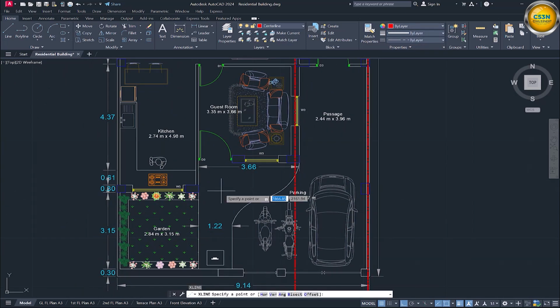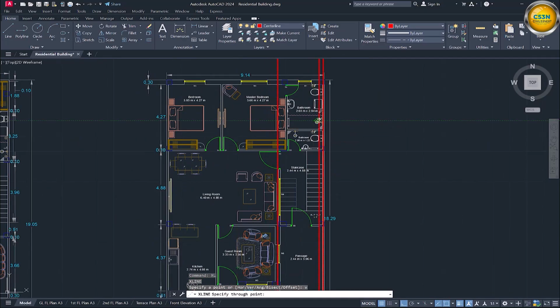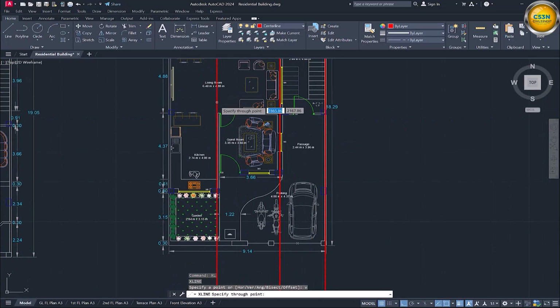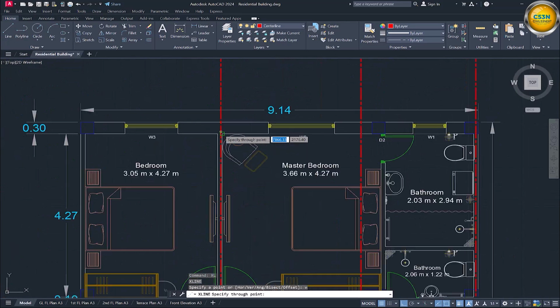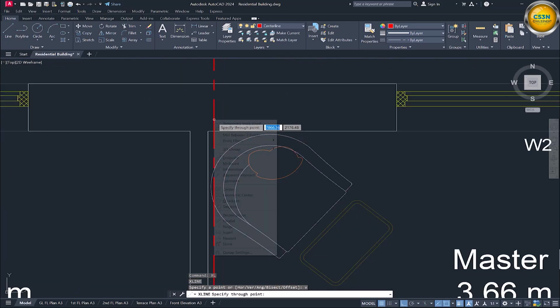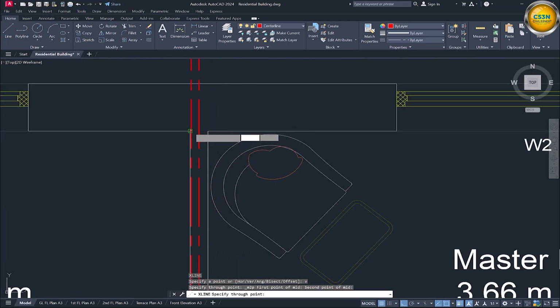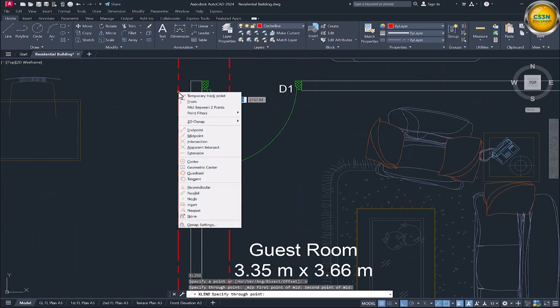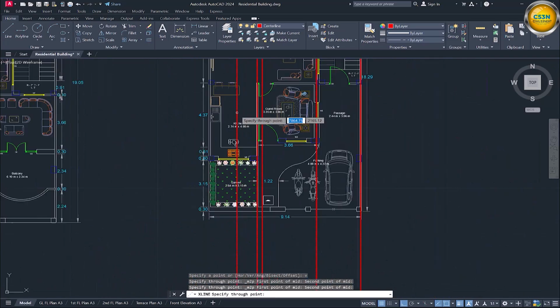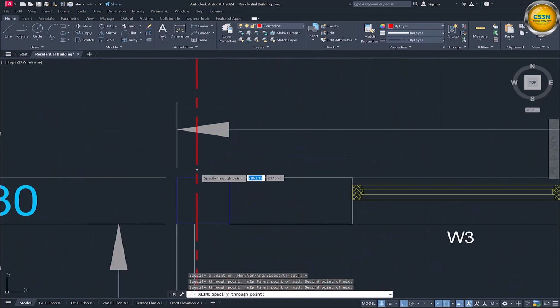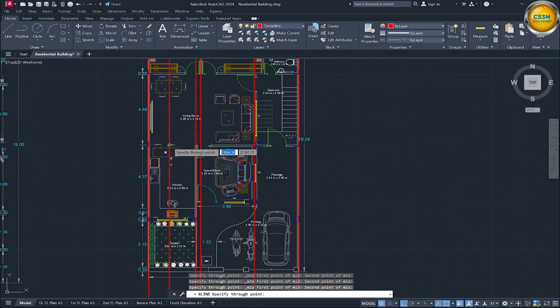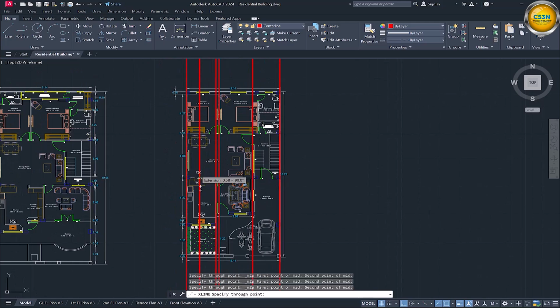XL, enter. V here is in blue color, which means it's the shortcut. So type V for vertical, enter. Do we have another wall here? There is a second one, this one now. Since there is none, we can place it here. So it's between 2 points. Finally here, mid between 2 points, 1, 2. So we are done with our vertical construction line.